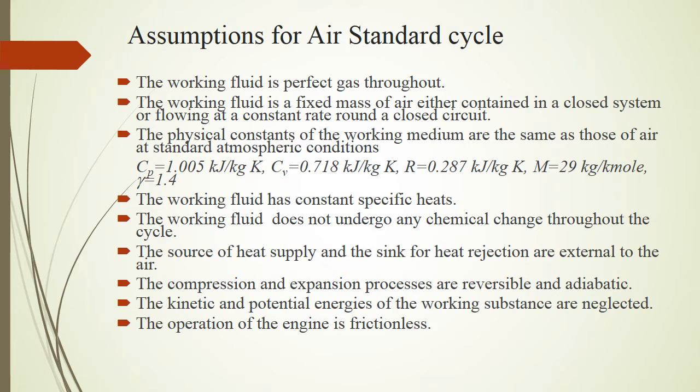Now one must be wondering why, after all, the accurate analysis of IC engine cycle is very difficult. That is because of the complex chemical reactions taking place during combustion, and moreover because of the friction and heat transfer present between the gases and the cylinder walls. So what is the way out?